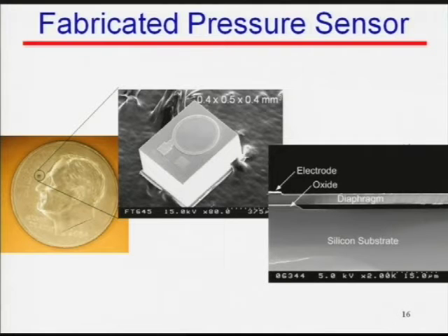Before I come here, I deleted two pages on the fabrication process because of the time constraint, but I'm going to show you that after going through the MEMS fabrication process, this definitely can be done. A lot of papers have been written from results fabricated at the MFL on the third floor of Bingham. This is the SEM picture of the pressure sensor. You can see that it's less than 0.5 millimeter by 0.5 millimeter by 0.5 millimeter in size.